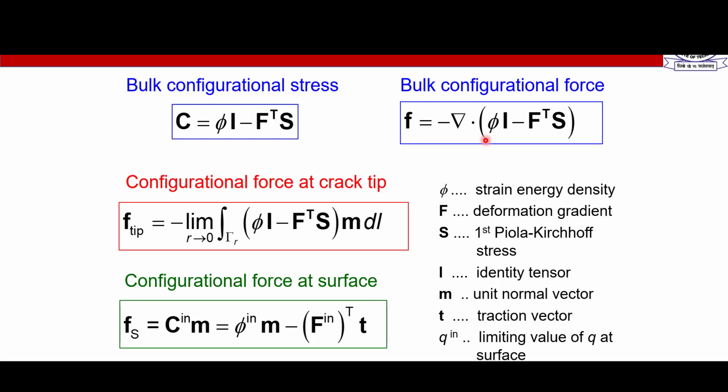So the J integral of Rice can give you the material's resistance, but it cannot describe the driving force on a crack, okay? Because plasticity cannot contribute to the force which can drive a crack. So here we can calculate these forces in two different ways.